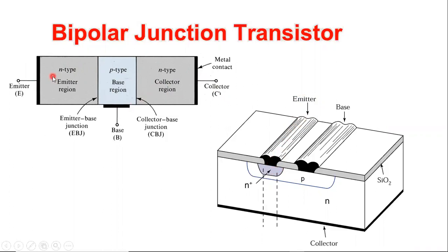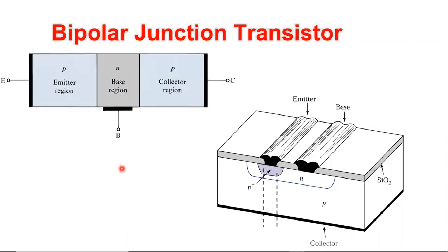Something like we did in the MOSFET. However, we have to remember that the MOSFET is basically a 4-terminal device. It includes the source, the drain, the gate, and the body. Most of the time, the body is either connected to the ground or connected to the source. But here, the BJT is basically a 3-terminal device, as you can see, and this is a famous circuit model for the BJT. I believe you dealt with such a model in Electronics 1 or Electronics 2 in your previous years. We have another type of bipolar junction transistor, which is a PNP junction.